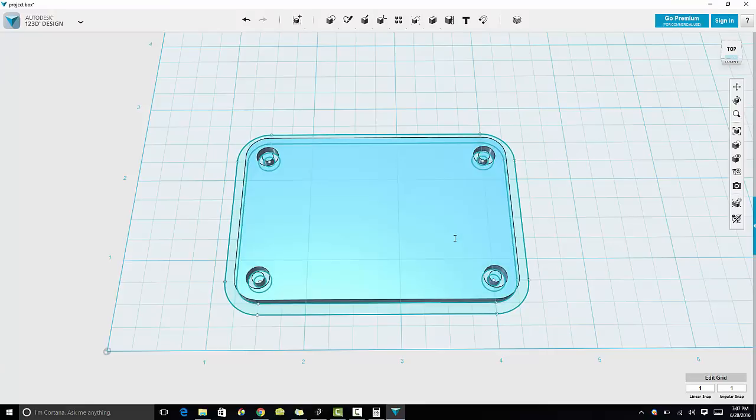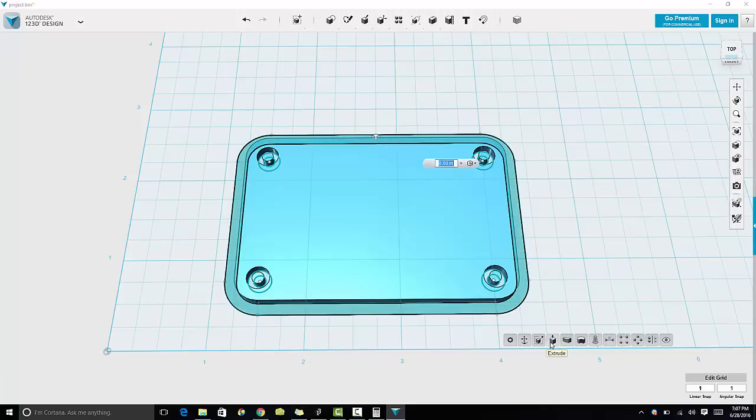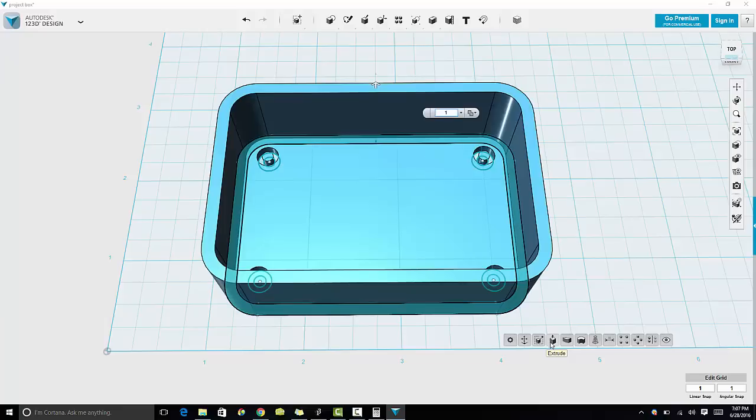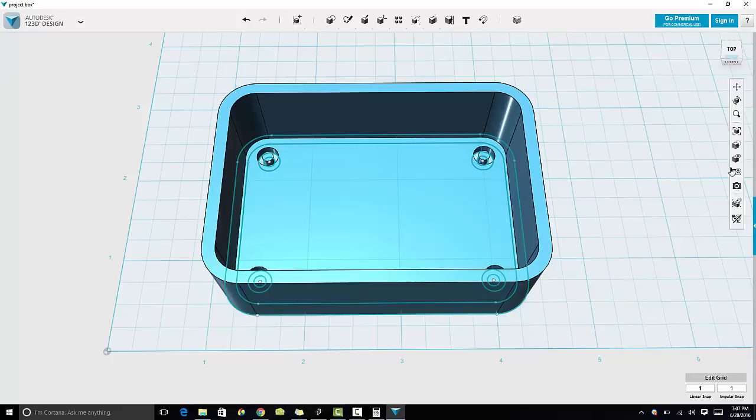All I'm doing is making everything 1/8 of an inch thick, to make it nice and strong, so there's a good bond. If I go thinner than that, I can pretty much break it with my hand. If I go this much, it's really hard to break it with your hand. So 1/8 inch thick is a nice round number, and pretty good. That's why I always choose that number. The next thing we're going to do is click on this outer shape, and you guessed it, it's a 3x2x1 box, right? So I'm going to add 1 to that and make that 1 inch.